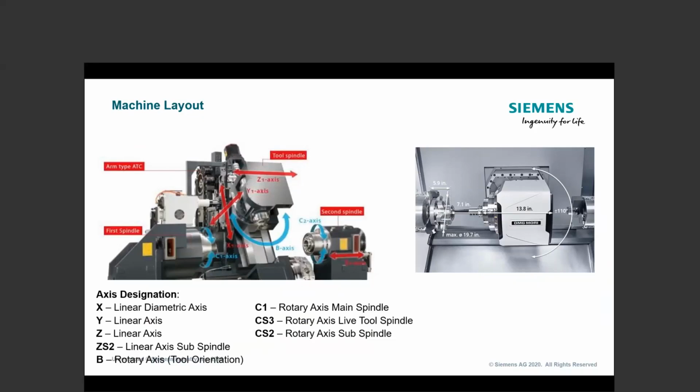Well, generally speaking, most builders, when they commission a B-axis lathe, will set B0 at 9 o'clock. And generally because that's usually the orientation as well for tool change. So when you do get on this B-axis lathe, not only do I have to get my axis designation down, but I have to know where that B datum is, because everything's going to drive from that. All of our tool orientations are going to be based on this location. So if I have to jog it to position, then that's what I will do right off the get-go. But generally speaking, you should expect B0 would be at 9 o'clock. So B of positive 90 degrees would then swing that tool down to 6 o'clock.